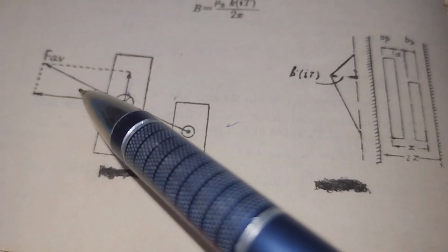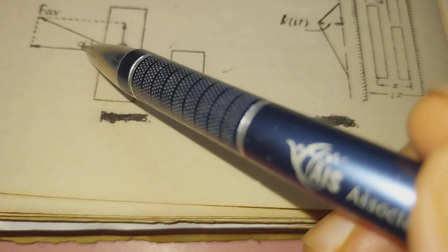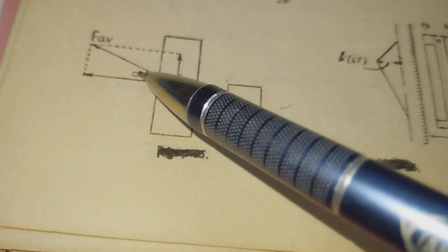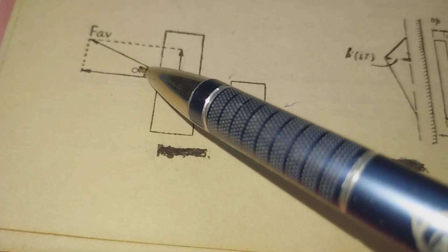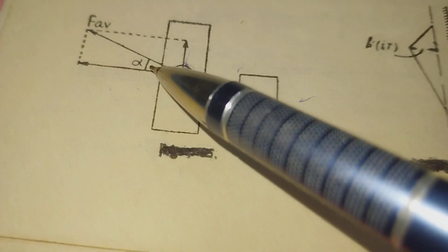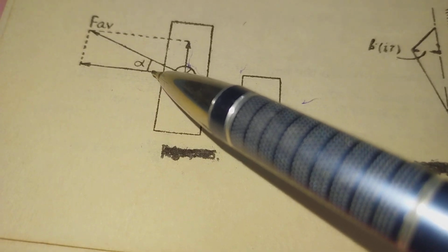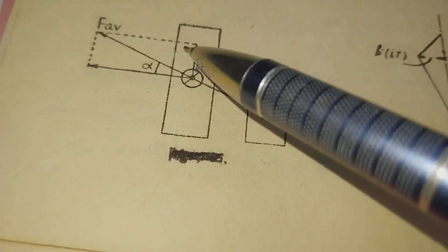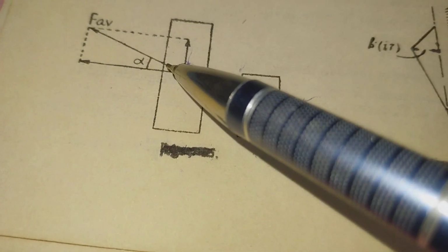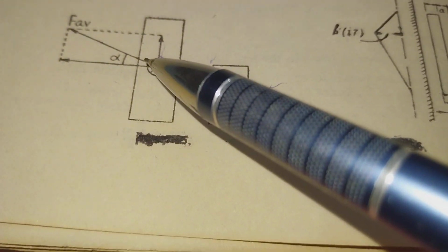The axial component may easily take a value such that there is failure in the transformer unless necessary bracings are done to prevent motion of the coil along the axial direction.